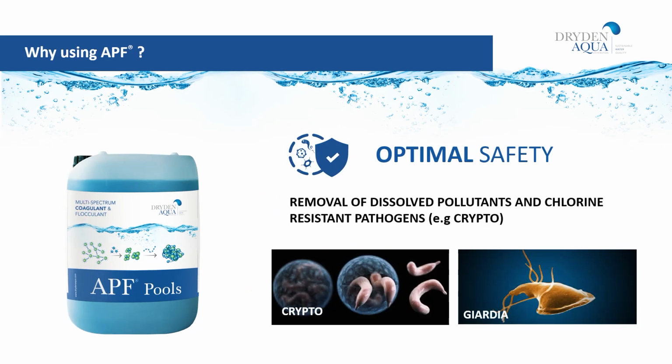And it's reinforcing and creating a better barrier against pathogens such as Cryptosporidia and even Giardia, which can be killed by chlorine eventually, but that does take some time. So it's better to filter these pathogens out rather than to try and destroy them with high levels of chemistry.